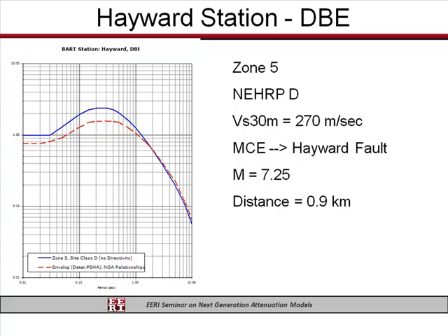What was done before in the 2002 model retrofit program was to basically fit expected PSV and PSD spectral shapes and extend those out by form fitting or equation fitting. And so now with the NGA relationships, we have a better understanding and a little bit more robust in estimating ground motions out to these longer periods.